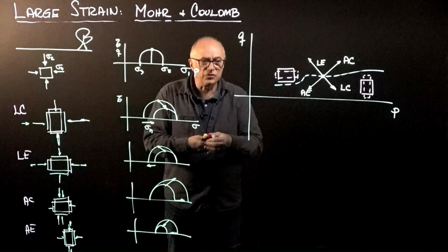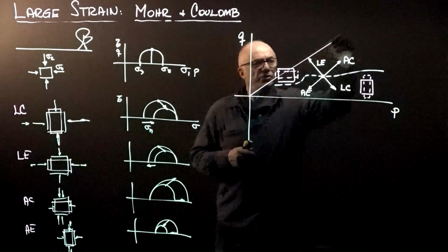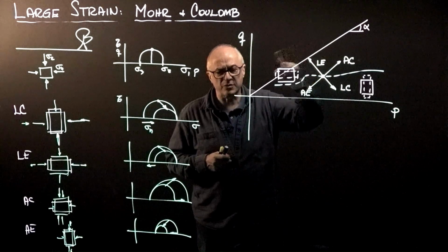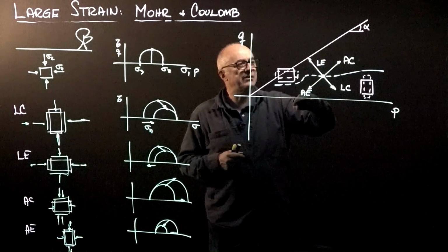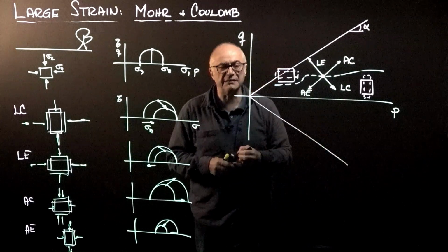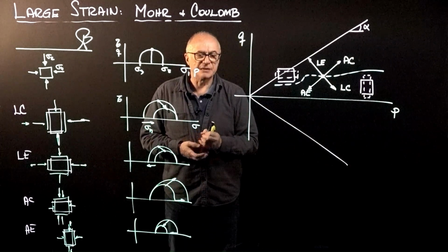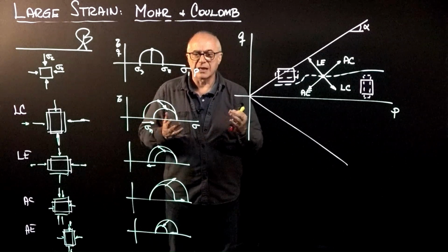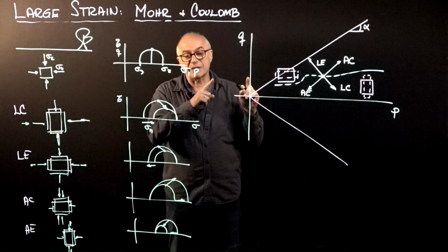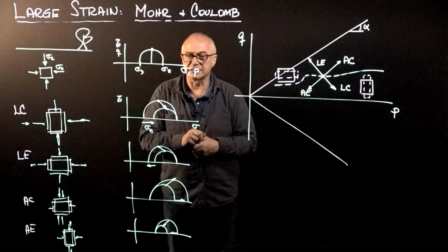Of course, this is going to be limited by the limiting anisotropy. So these paths are going to encounter what we now call the alpha plane. Remember, tangent alpha is equal to sine phi, and they're going to encounter this failure plane in the upper part or in the lower part. So that is the limiting equilibrium condition. When we look at the coupled behavior between pore fluid generation and deformation, we're going to see that these stress paths apply only for drained conditions, and the story becomes more complex under undrained conditions.